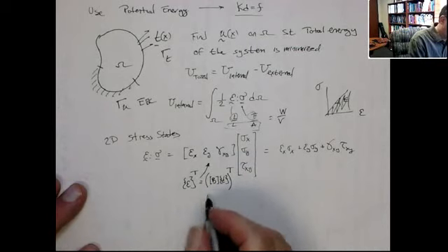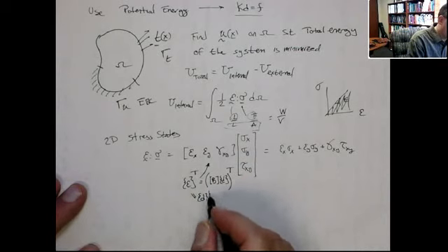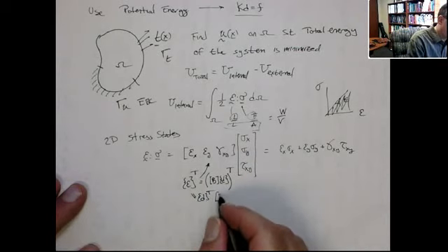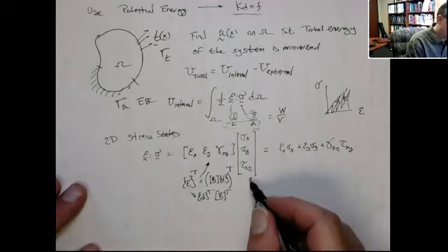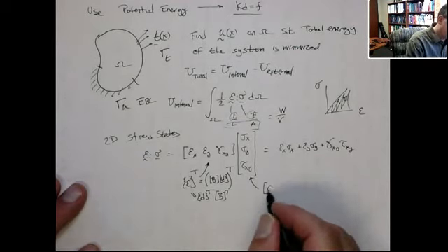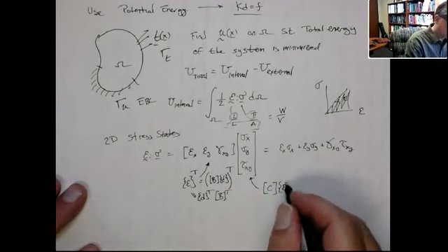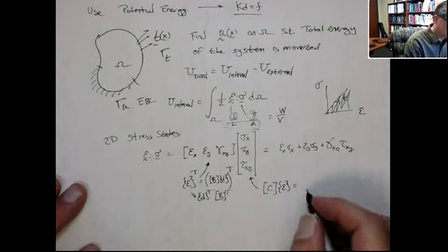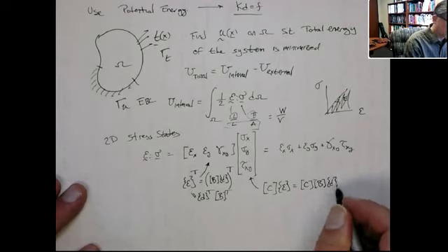So this term here is actually going to just be D transpose, the row vector, times B transpose, okay? Now likewise, this stress in Voigt form, we can write as the material stiffness matrix, C, times the strain. And the strain we can write as B times D. So this gives us C times B times D, if you will.